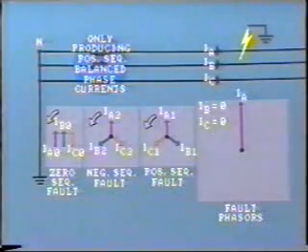So we now come to another very important conclusion, and that is where a ground fault exists, all 3 sets of symmetrical components are present. That is, positive sequence components, negative sequence components, and zero sequence components. And do note that within each set of components, the voltages and currents are of equal magnitude. The presence of these components provides a useful tool for detecting unbalanced conditions and ground faults.